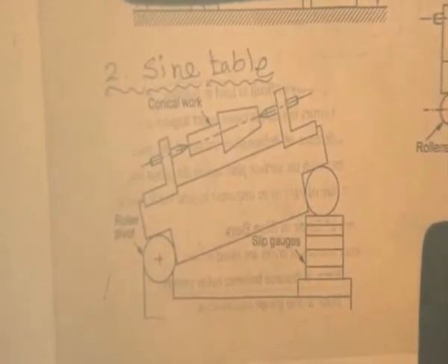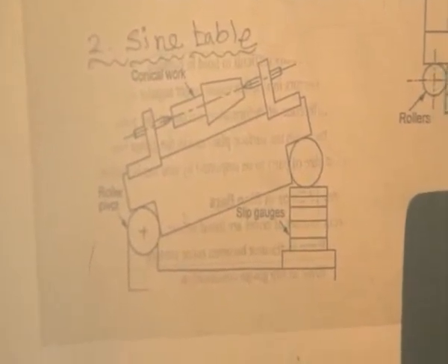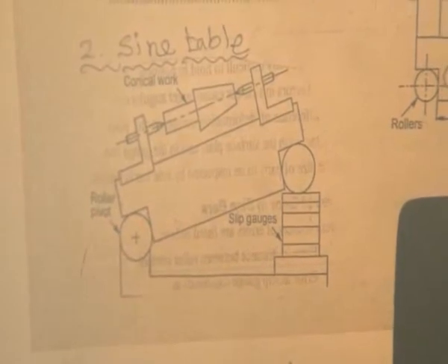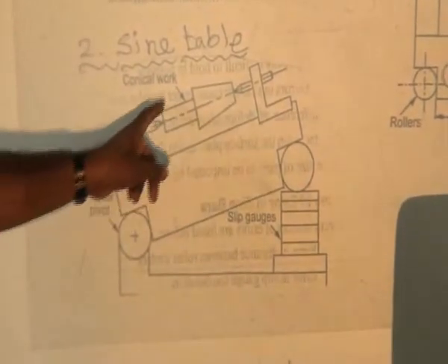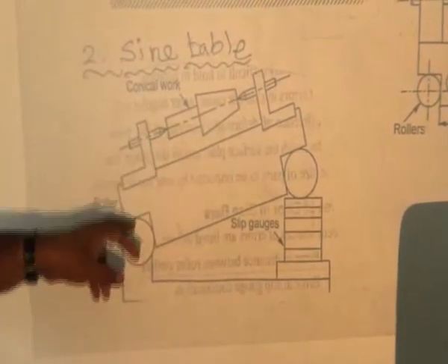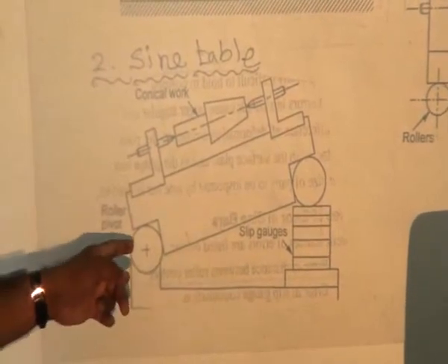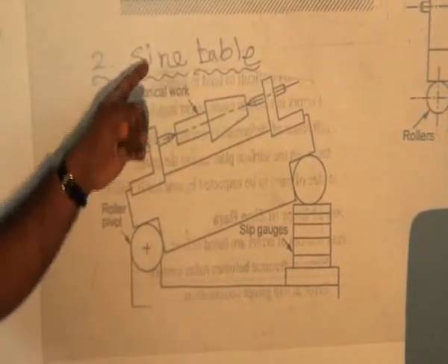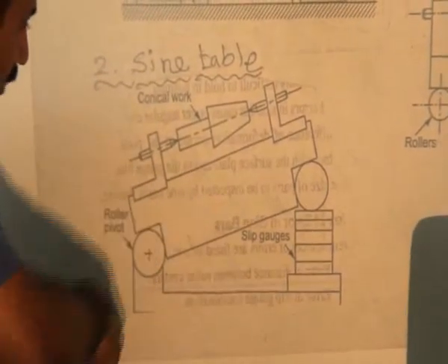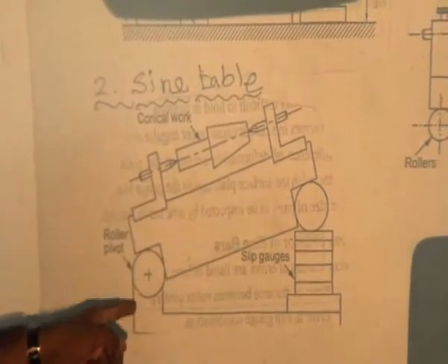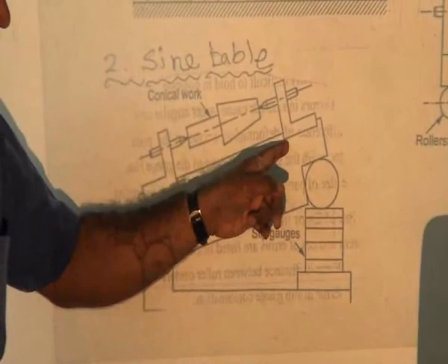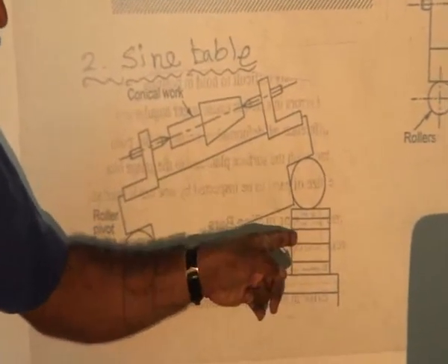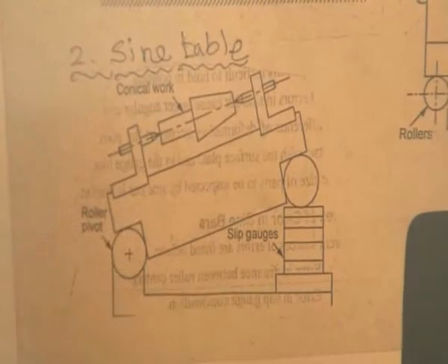In that component, one of the surfaces is a rectangular or square surface and the other is an inclined surface, so it is easy to clamp using the sine bar. But this conical surface we cannot measure the inclination of with it. That's why we modify it. The modification is very important. One end of the sine bar is pivoted on the table. That is the main thing. The other end is easily moved upward and downward.